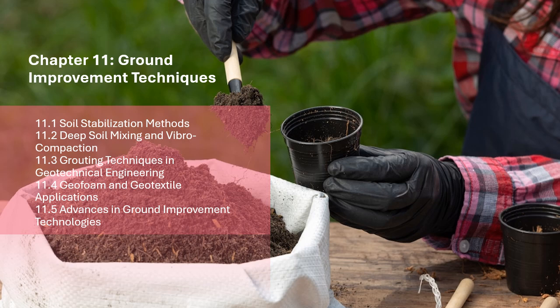Example: in areas with soft soils or where ground improvement is difficult, geofoam is used in embankments or road construction to avoid differential settlement.